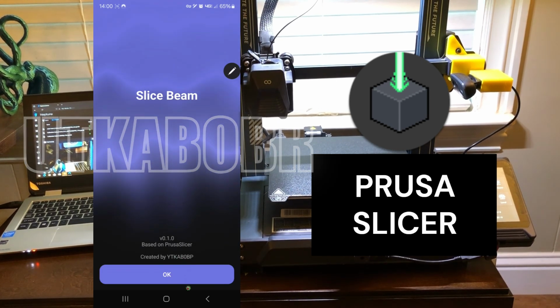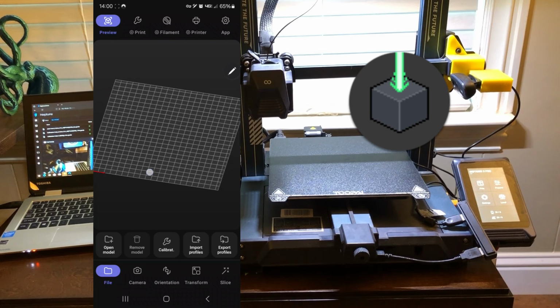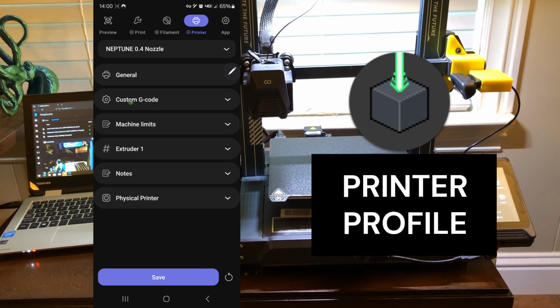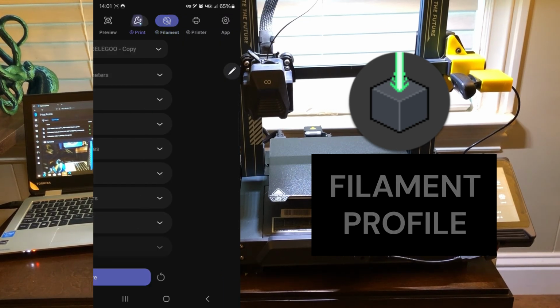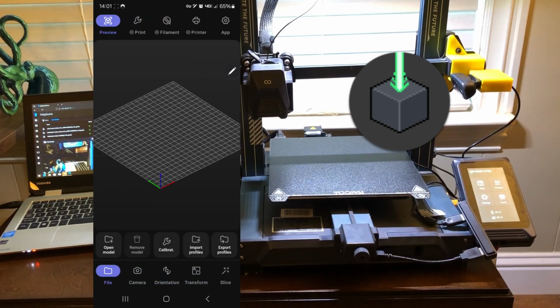As you can see here, the slicer is based off of Prusa Slicer, which allows you to create or import your existing Prusa Slicer profiles. Starting off with the printer profile where you can input your machine limits, then followed by the filament profile where you can tune your material and cooling settings, and lastly the print profile where you can adjust layer heights, infill, supports, and speeds.